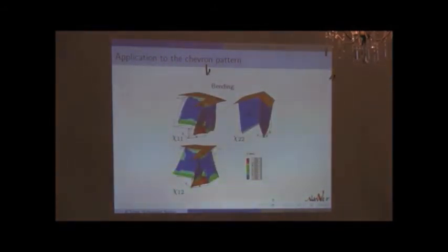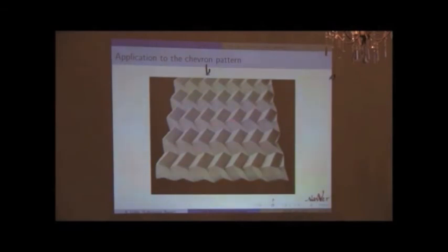If I do that, I show you first the bending computation on the RVE. You recognize here in orange the upper skin and the lower skin, and this is the fold, mostly in blue. It is just a unit cell of the fold, a bit more folded.